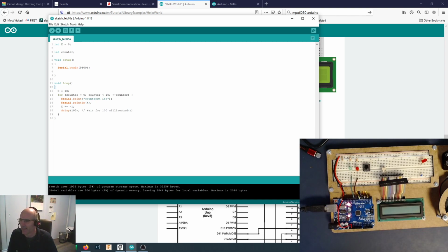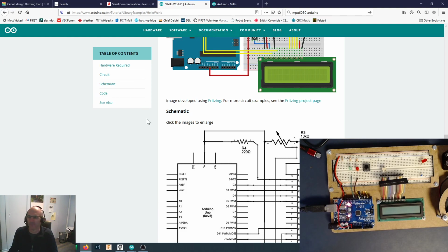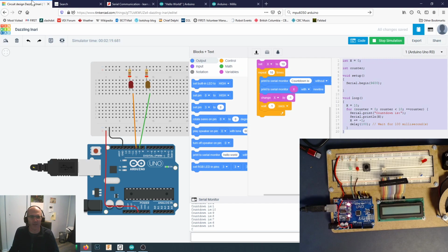The cool thing is printing to this actually works a lot like printing to your computer, and the code that comes in the Arduino IDE takes care of the fact that you're doing serial communications here, but you'll do parallel communications to this particular LCD screen. Okay, so go ahead, try the serial print, get that serial monitor up and running. You'll find lots of useful tutorials out there about all the different things you can do with the serial print command.